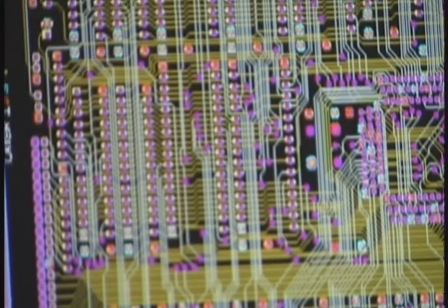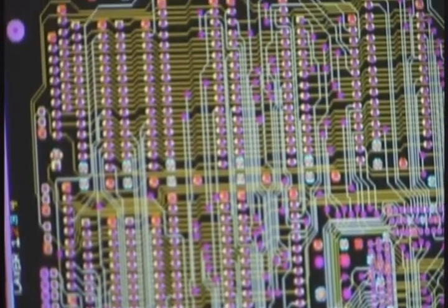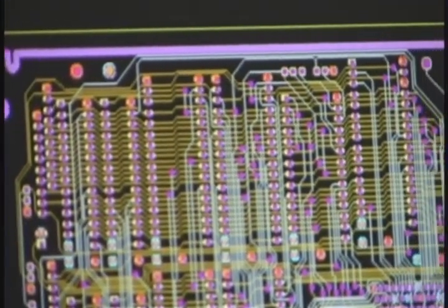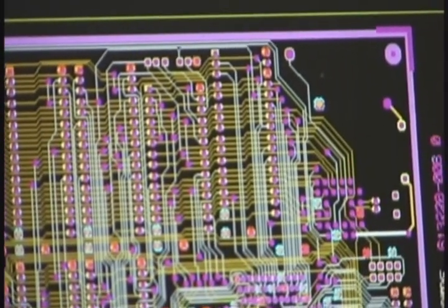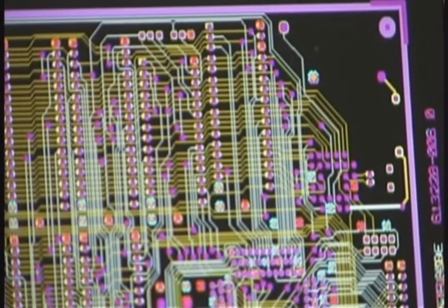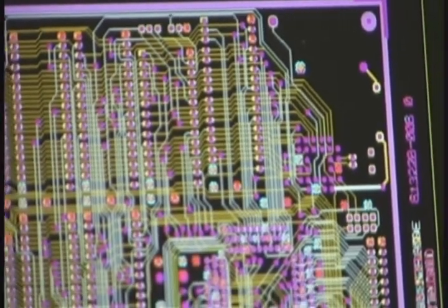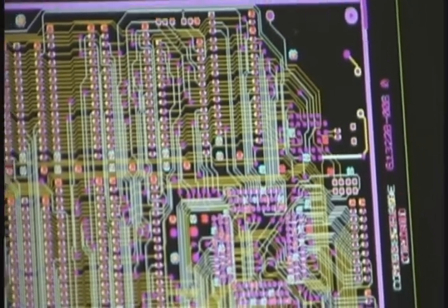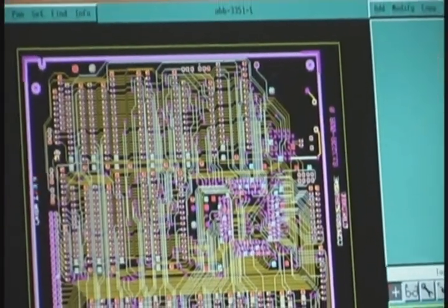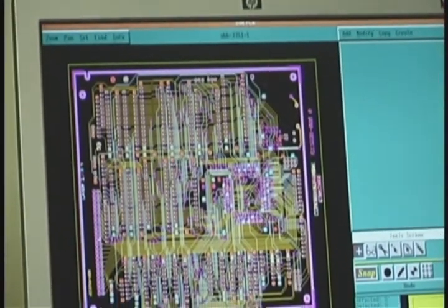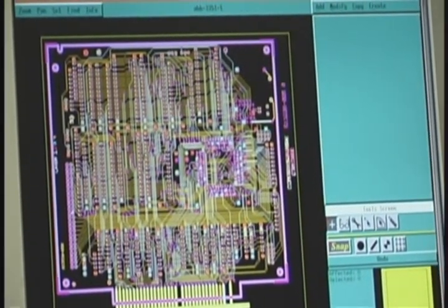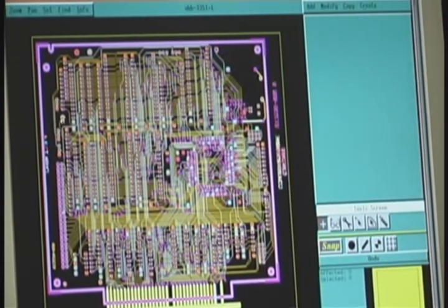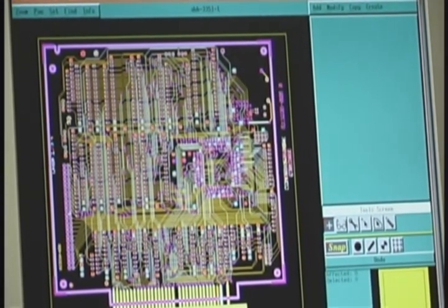For the QC stage, what we do is we will plot the files that we generated from the contoured layers, and then we will plot the job, and then we will make a diazo shot of those Gerber files and a diazo shot of the Gerber originals, the originals that the customer sent, and from there it will go to the QC department, and the QC department will perform the inspection.